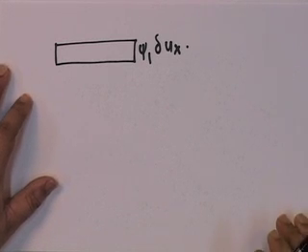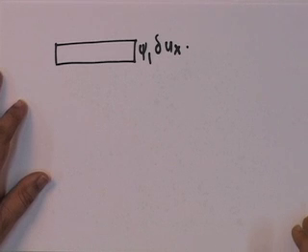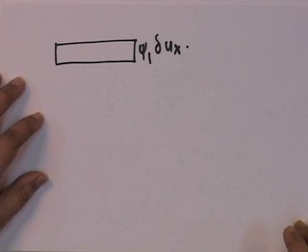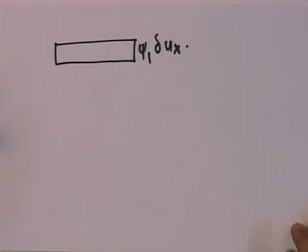All I have to do for getting two equations is write down virtual work equations for two different, linearly independent displacements. Since my degrees of freedom are independent, I always take displacements corresponding to the degrees of freedom. I know that they are independent, so then I can get two independent equations.